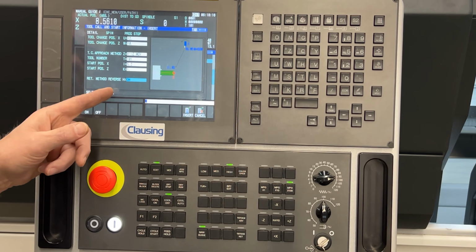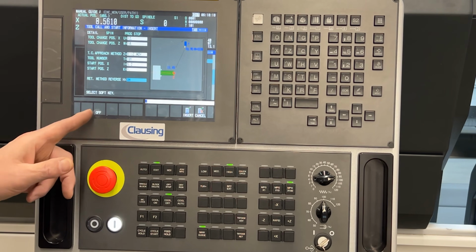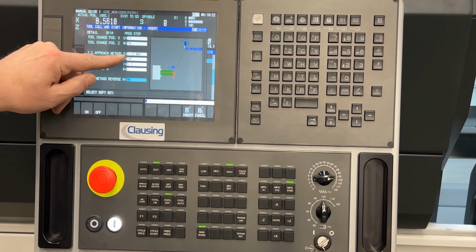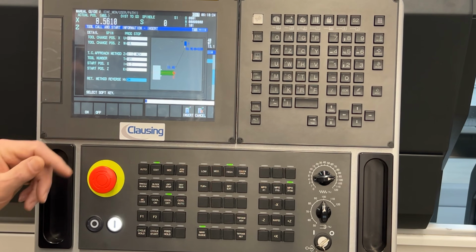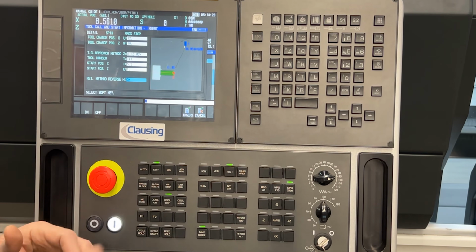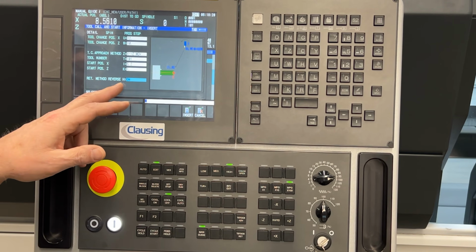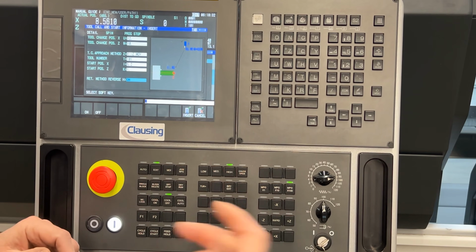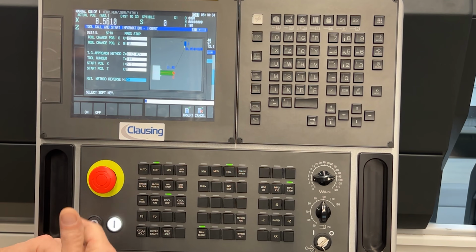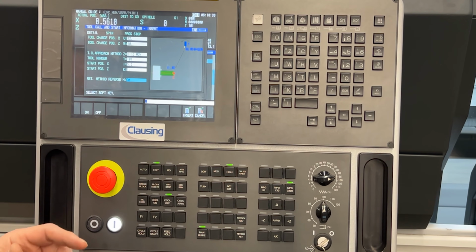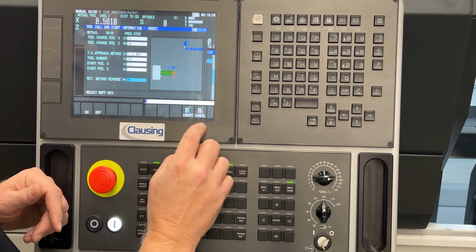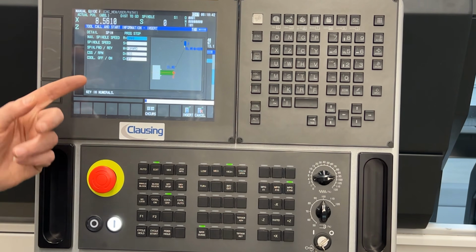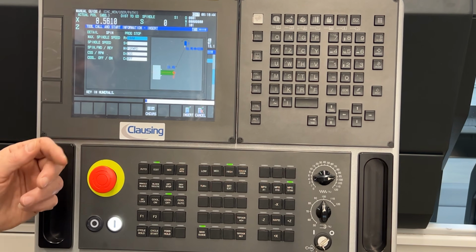The return method, reverse on or off by these two selections, is that however it went to the tool change, in this case it was X first then Z, if I have the reverse method on back down to the part, then it's going to do Z first then X. So if we have to get around something, that's a good safe way of doing it. So I've got that in there. I'll hit input to go to the next bits of information.